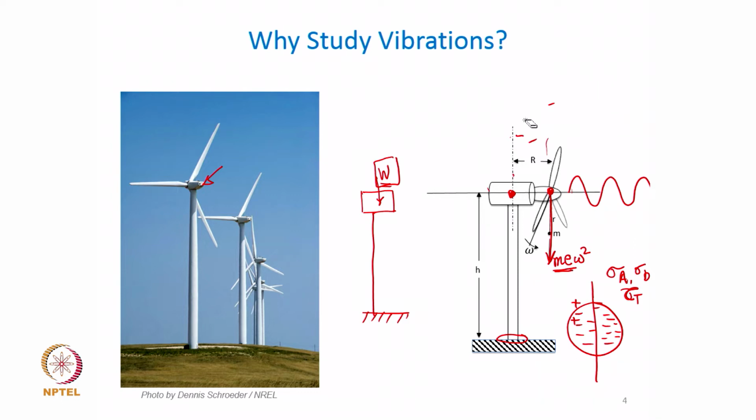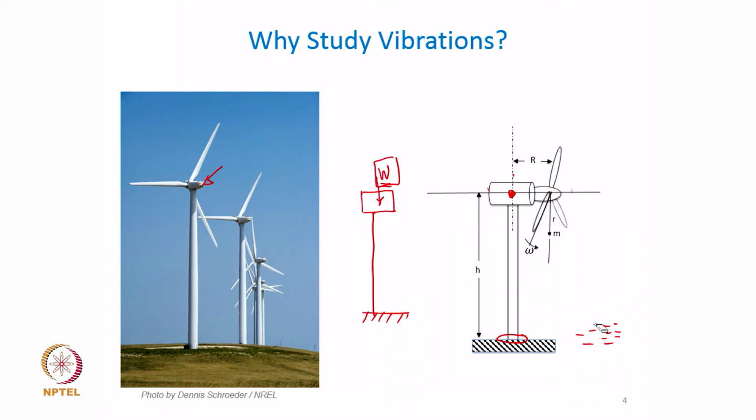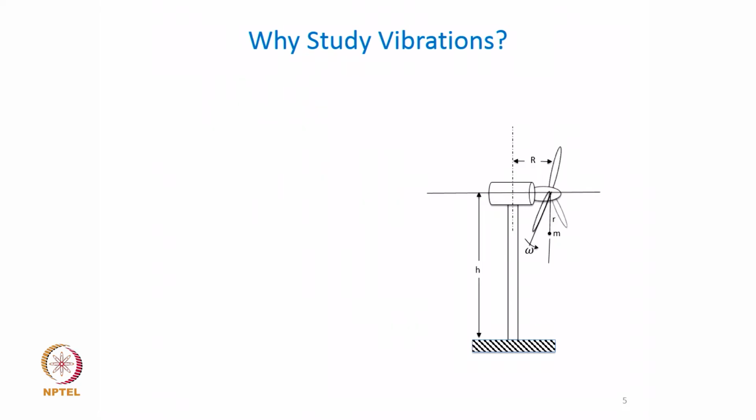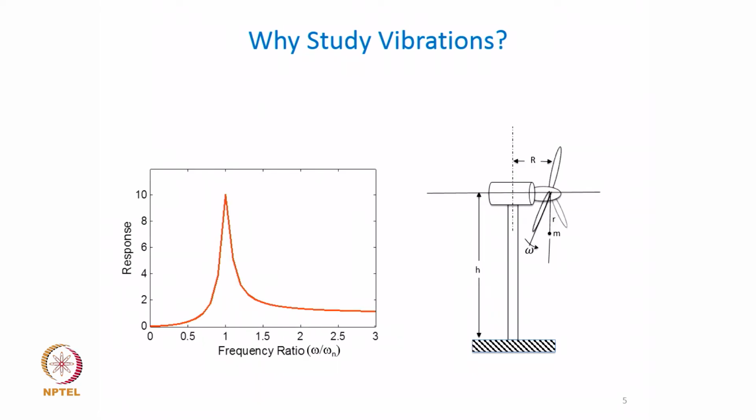So, if we really do this design based on only these dynamic forces, we might end up in trouble because we are probably missing an important element here, and that is if these excitation forces which are generated as we discussed in the previous slide, if they get into a situation which generates resonance in this structure, we can have the dynamic response of this column generating deflection several times the amplitudes which are otherwise expected or planned by the designer.